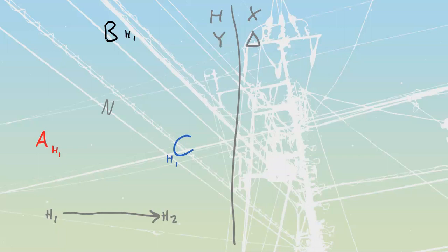Okay, we're going to start with our A phase, and we see that we have an H1 already there. H1 is going to be the tail, H2 is going to be the head, and we know that our H1 is going to go across from our A to our B. H2. Oh, sorry, what am I doing? A to our neutral, because we're doing a Y side. I just lost track of where I was for a second there. So I'm going to start with my H1, and I'm going to take my H2 into the center.